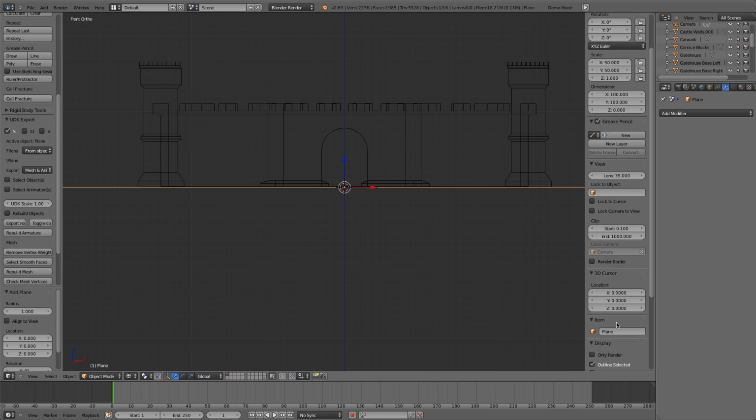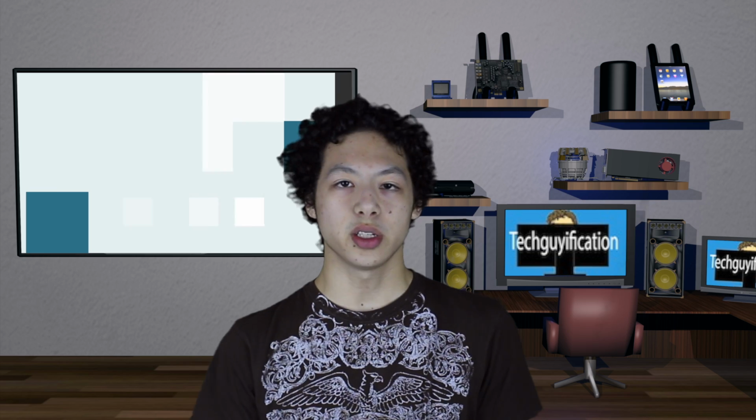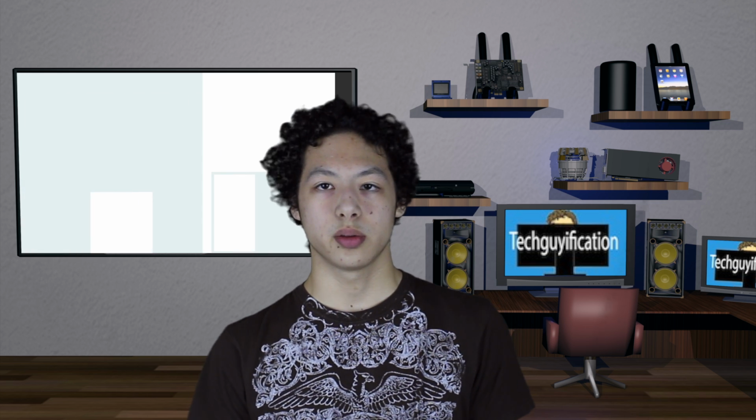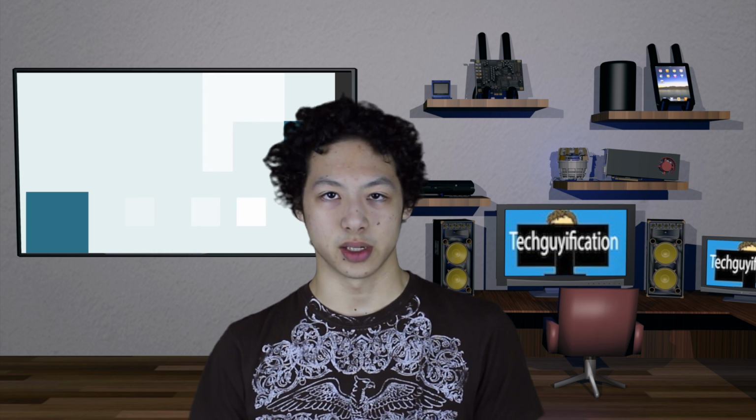And in that toolbar, name this object Ground. Now go back into solid display if you're not already in there by pressing Z on the keyboard, and you can rotate and pan the camera to see all that we've done so far.